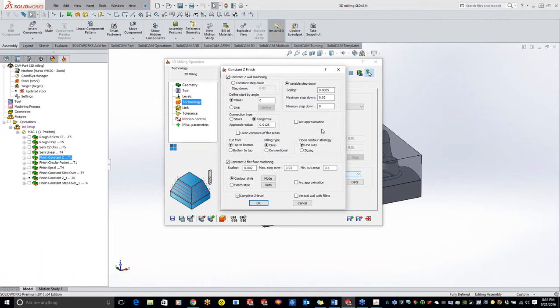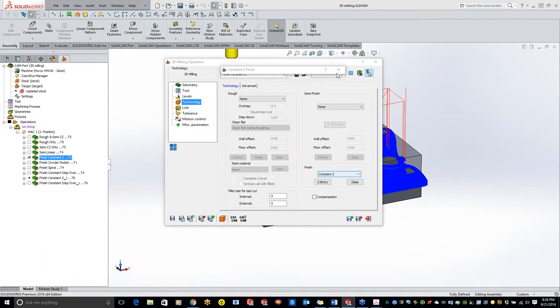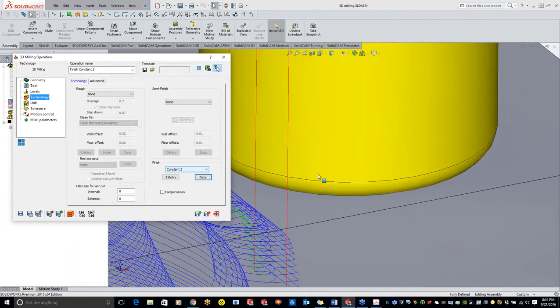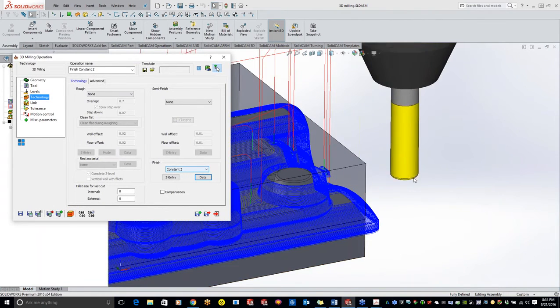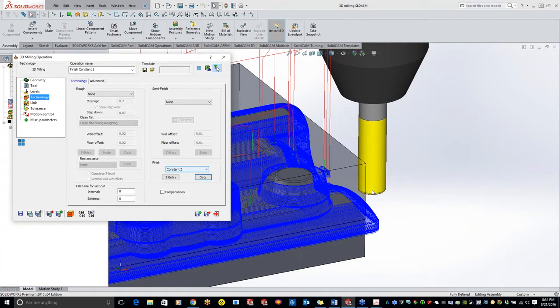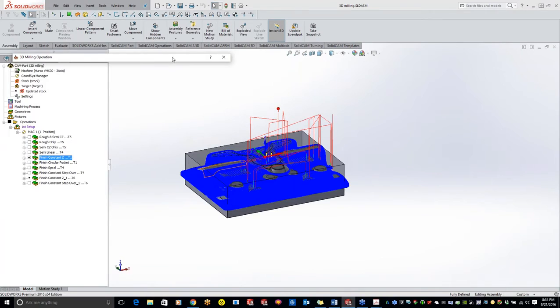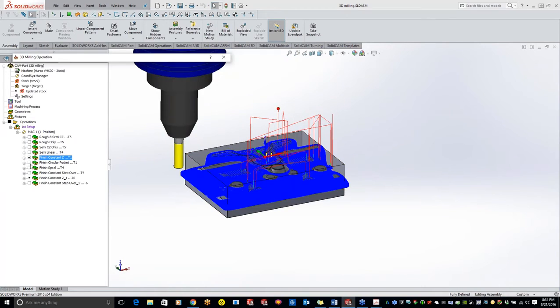connections, and the connections, if I didn't cover that well enough before, the connections is your paths that are, let me just shut up and I'll just show you. So the connections are your movements that come outside of the part. So we don't really have a lot of connections right here on this particular toolpath, but with our linear path that was just doing zigzags back and forth, the connections is between those lines.